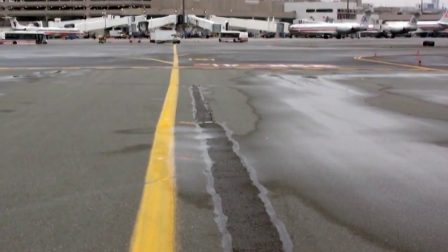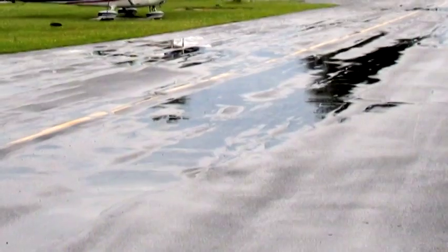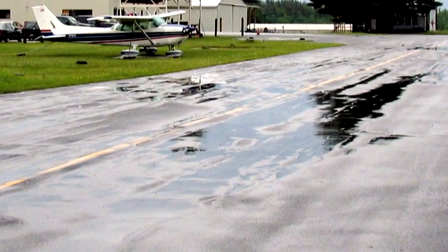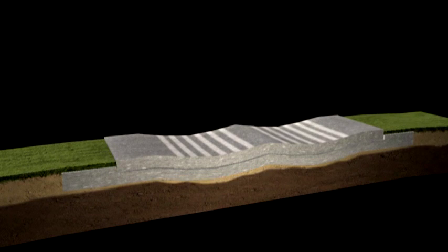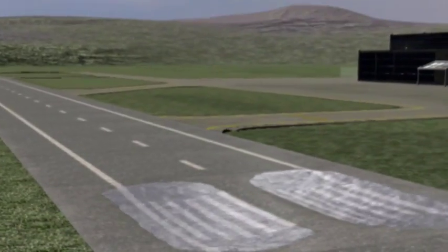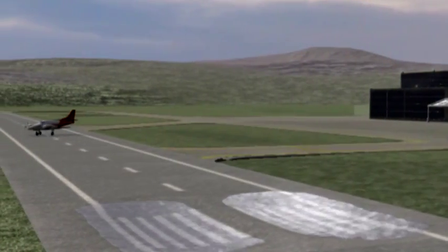Any bumps or low spots in the pavement should be reported, since bumps can affect directional control and obviously water can collect in a low spot, causing ponding. Touchdown zones on runways used by large aircraft are particularly susceptible to developing ruts. Standing water on runways is particularly dangerous since it can cause aircraft hydroplaning. And water also tends to obscure pavement markings, especially at night.